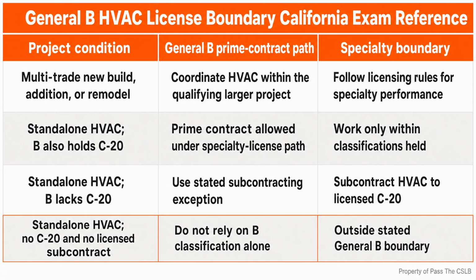The three manual names are easy to blend together, so I separate them by the question each one answers. Manual J answers, what is the building load? It is the heating and cooling load calculation. It accounts for the thermal characteristics of the specific building, including factors such as orientation, insulation, window performance, and climate.